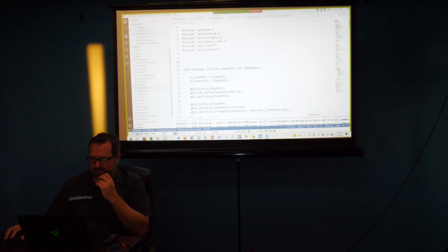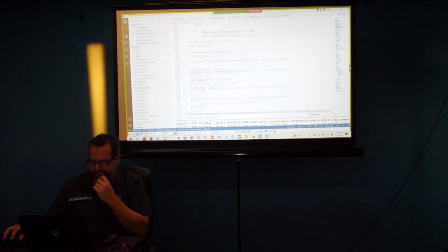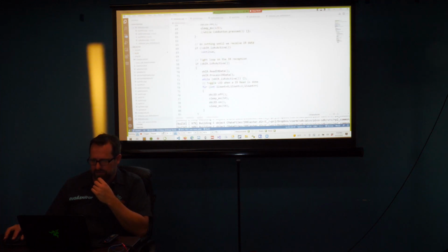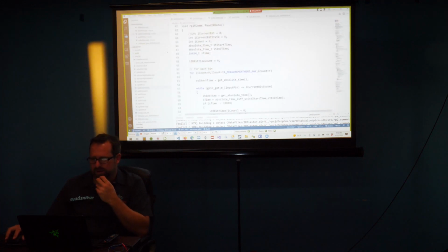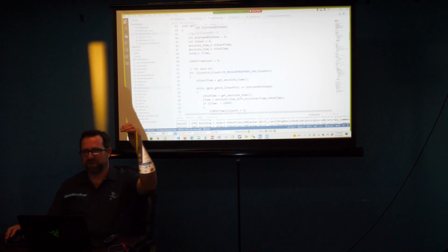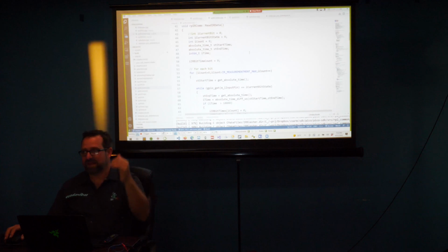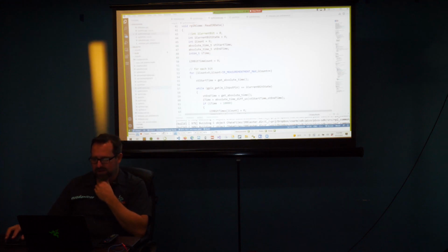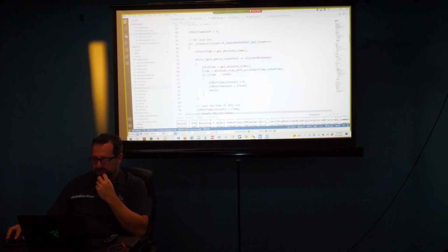But anyway, let's look at the big ugly code. The first step is read IR data. All right, so here's our read IR data. This is called when the IR receive line goes low, so it's that first start bit, that first 8 or 9 millisecond bit. It gets called, and then it goes into a loop. This is going to loop to IR measurement max, which happens to be 120. For no reason, it was just me hacking.